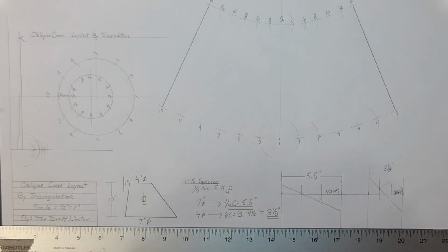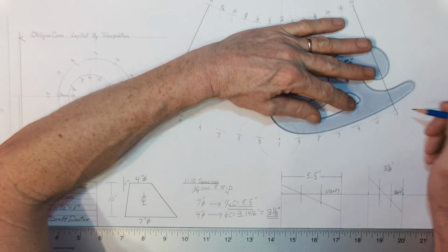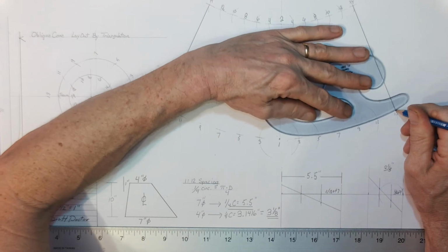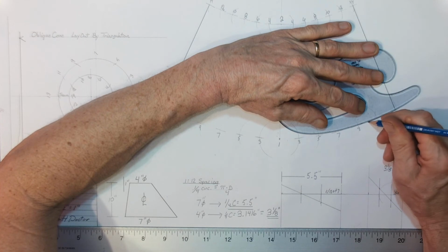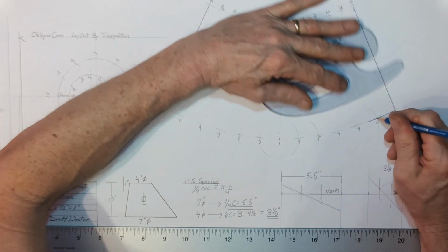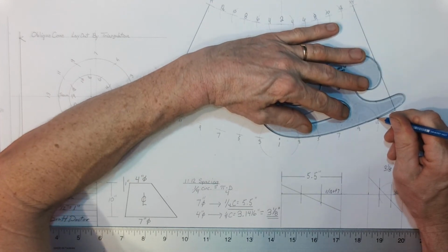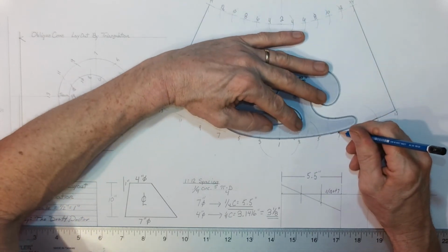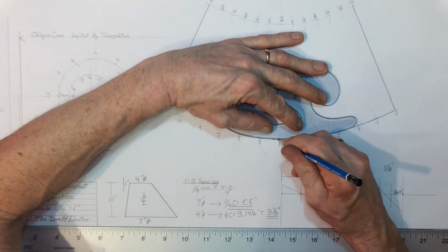And I thought I'd take this opportunity to show how to use a French curve to connect these. A lot of times I'll just connect them by hand, but what I like to do is put it on the point I want to start off, and I'm going to swing until I get a nice curve that works with my first point or two or three, and I'm going to go past the first point and stop there. Then I'm going to go back to that second point. I'm going to see if I can't connect a couple more. And that'll take me all the way to 7. I'm going to go just a little bit past it and start on my 7 again. Look at that. All the way through, it goes right to the 1. I can even go past there just a little bit, and I'm happy.